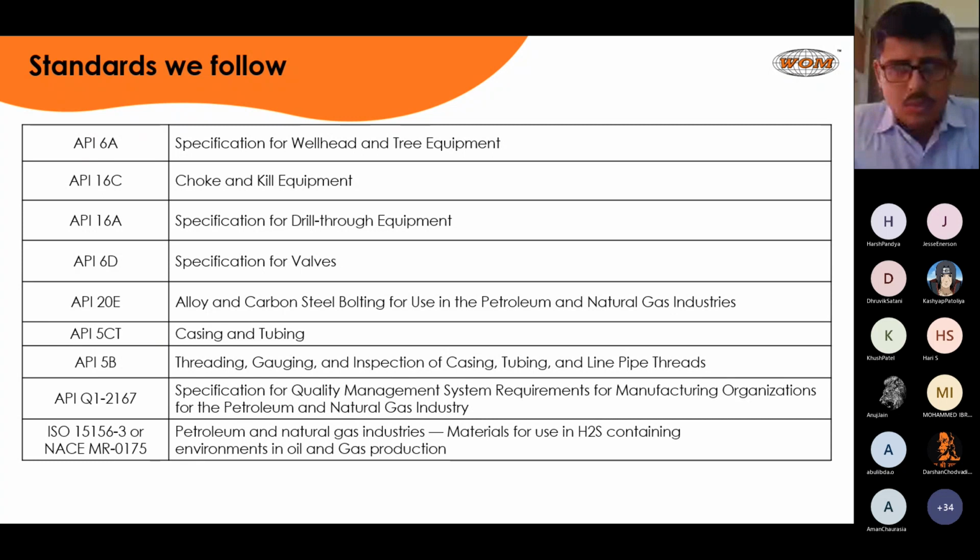The quality system we follow is API Q1 and ISO 9001, and there is ISO 15156-3 or NACE, National Association of Corrosion Engineers, MR0175.